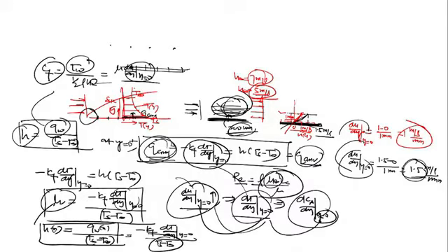Here it is wall heat flux, there it is wall momentum flux. But I told you, just like this, for the calculation of the friction coefficient through this formula, you must have knowledge of the velocity gradient; the velocity profile must be known. Then only, u is a function of y given, you differentiate and put y equal to 0 and find the friction coefficient at that point. Yes or no?